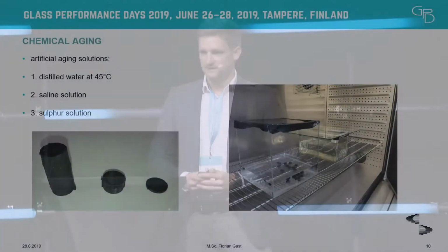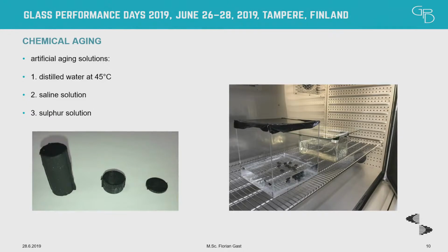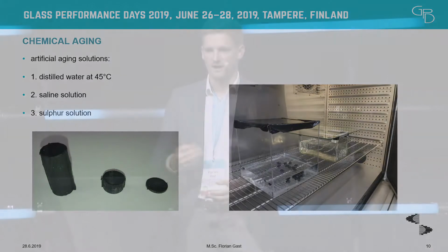So what I did, I had cylinder samples. You can see here, the basic sample was 30 millimeters high with a diameter of 15 millimeters. And I aged these and then cut out smaller samples for the different methods I used. The medium one is 8 millimeters high, and I took that for microcomputer tomography, and the really small plate is only 1 millimeter, also cut out precisely, for infrared spectroscopy. I will show you on the next slides.